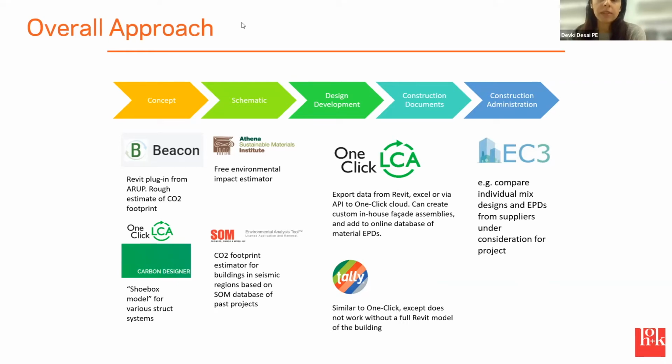Something to know about EC3 is you can just log in and start using it, but it doesn't look at the entire product lifecycle. It just looks at everything from cradle to gate, which is materials extraction to manufacture, to the point at which it arrives on site. Everything beyond that point, which relates to maintenance, disposal, end of life, and recycling, is not really included in EC3. So it's important to note that that is not a full life cycle analysis, but it can certainly help you choose between products.